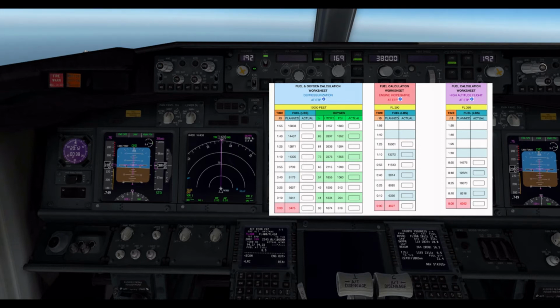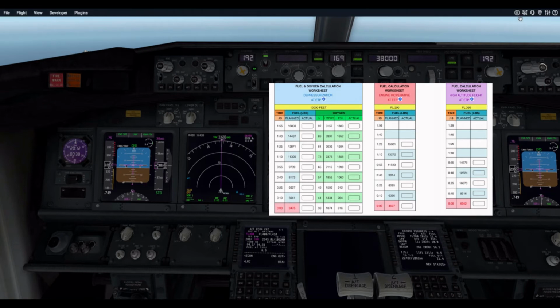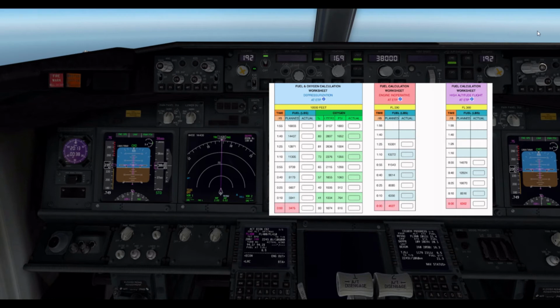The next green data set is an oxygen ladder. Oxygen reserves can be determined on the flight deck using percentage of full, liters remaining, or PSI, pounds per square inch remaining. The pilot will use the metric that applies to the aircraft he or she is flying. The calculation is based on predicted oxygen supply remaining at the equal time point, and then predicted consumption based on 15-minute intervals provided by Aeronautical Data Systems. The column labeled actual is to record the actual amount of oxygen remaining, just like we've done for the fuel.